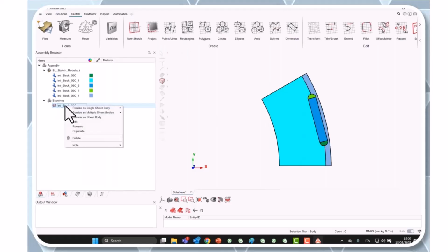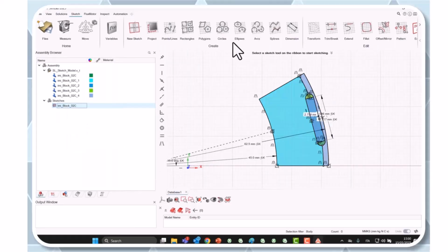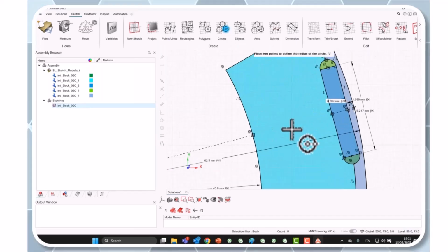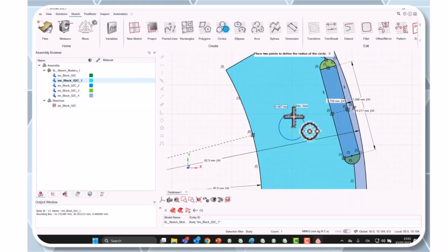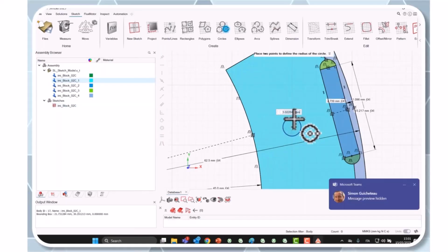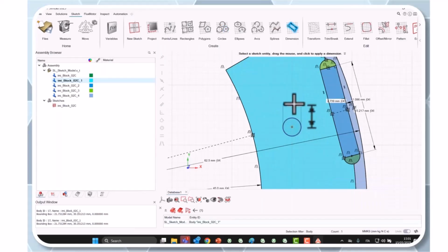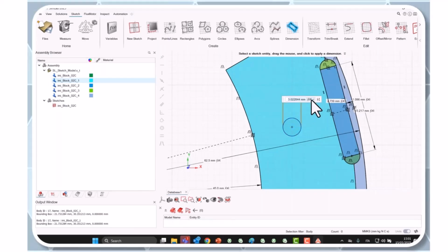So you can edit the sketcher, for example, adding a hole if you want, or do some modifications that can reflect your part in general. You can see that we have all the constraints of the sketch for all the lines and all the things we have in the sketcher. You can also create new variables for the parts that you will create.